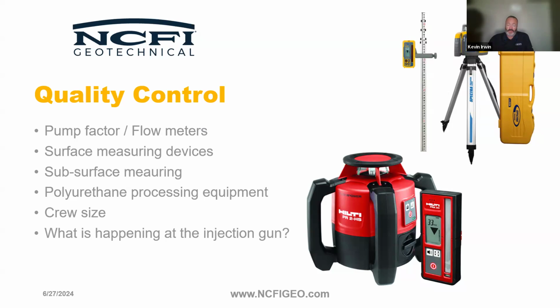Surface measuring devices, we talked about the laser levels, but subsurface measuring, there are dynamic cone penetrometers. They have a similar result to a standard penetration test that you might have a geotechnical engineer do. DCP, dynamic cone penetrometers, are available to an operator.